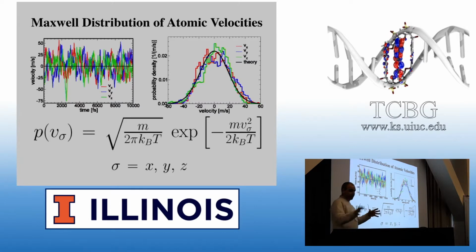You run one simulation where you have one system, you have prepared it, minimized it, it's ready to go. Now you can randomize the initial velocities using different seed numbers to make sure that they can be claimed as different simulations.